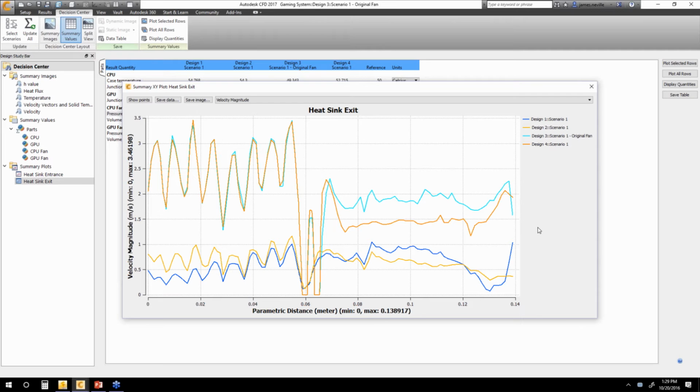Take a look at design 3 and 4, dramatically higher. I think I said 2 or 3 times higher performance, but it might be more like 4 or 5 times with design 3, higher airflow there. You can see just much better velocity performance, both at any point along the line, on the backside of these heat sinks, you're getting a lot better velocity there.